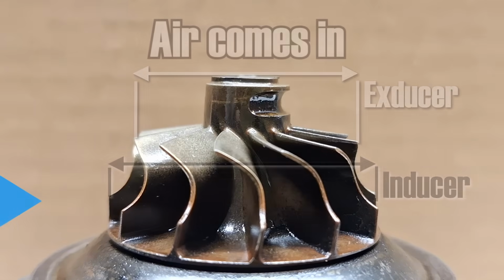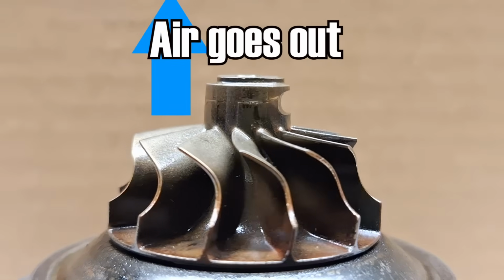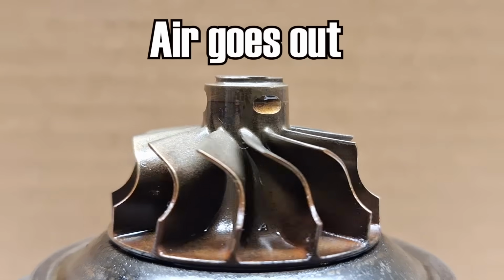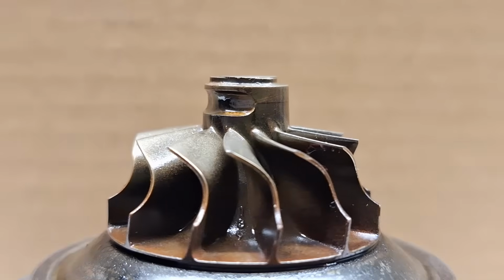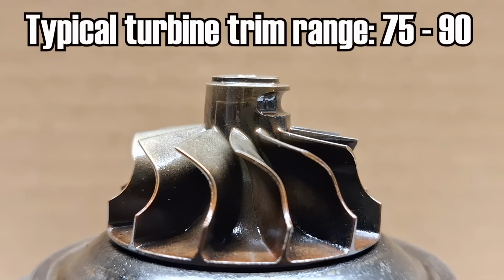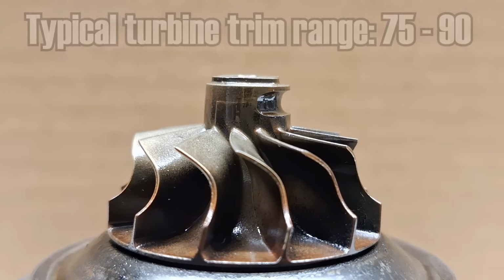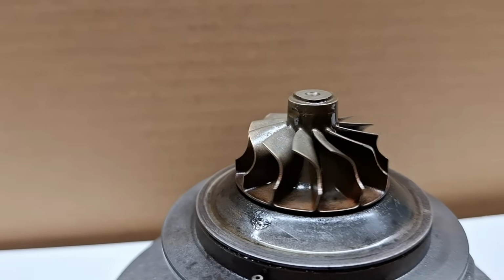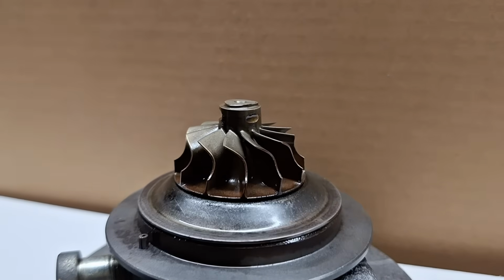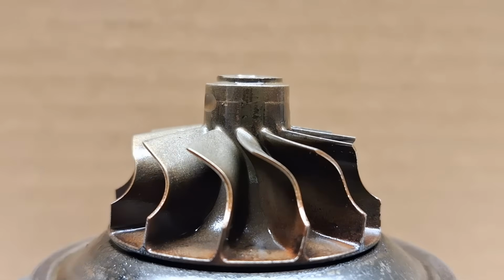This is because the air comes in and out in different directions at the turbine wheel. Turbine trim numbers will also be much higher compared to compressor trims, usually ranging somewhere between 75 to 90. This is because we have different airflow dynamics on the turbine side. We don't have to worry about surge, and we want to maximize the blade area for grabbing the exhaust gas in order to maximize the energy imparted onto the turbine wheel.